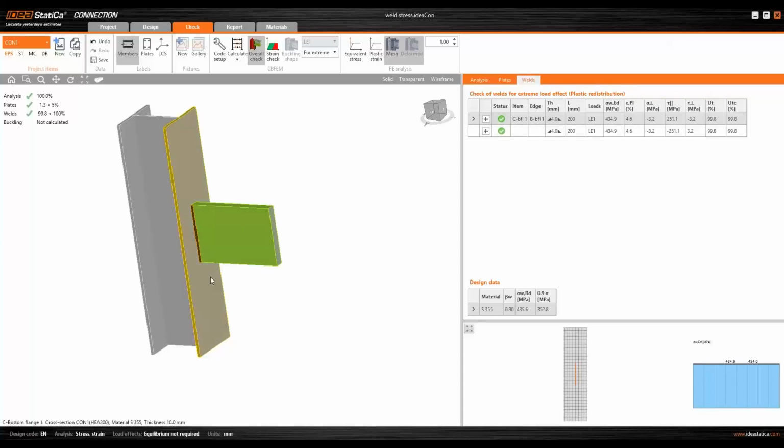Okay. So, I have also one question. It was regarding the DXF import of plate that you showed, and somebody had problems with it. So we maybe can just note what are the most usual sources of problems when you try to import a plate from AutoCAD. I think, Adam, it's usually that you have to disconnect all entities, right?